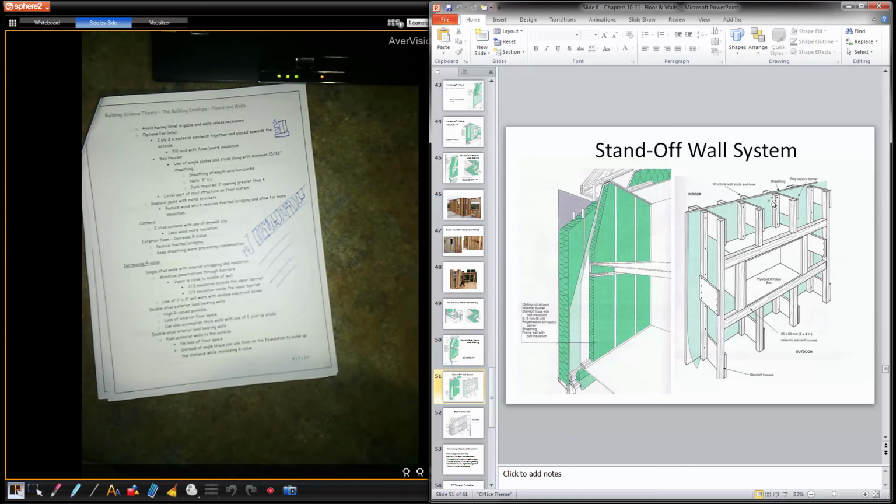If you're going to build a house this way, it has to be engineered. You can't just decide, okay, I'm going to put a 2x2 here, 2x2 here with 1/2 inch plywood. The engineer has to spec this, make sure it's correct, and that it's going to pass code. They probably even have to look at modeling to see how efficient it's going to be and make sure there are no problems with the system before you can go ahead and build. But this is passive home stuff. Okay. But again, almost a balloon frame, right? Balloon frame going through, ledger or floor onto the balloon frame.